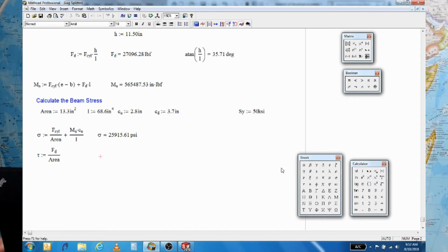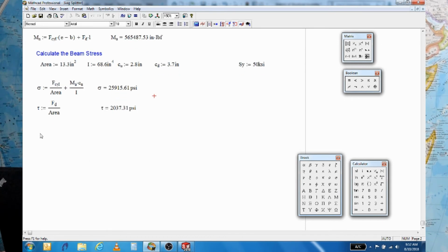And this number is probably going to be less than 1/10 of the other one, just because the failure mode is bending and not shear. We're not twisting this thing. We're not really having a short beam and trying to shear it off. All right, so that's what we do expect.